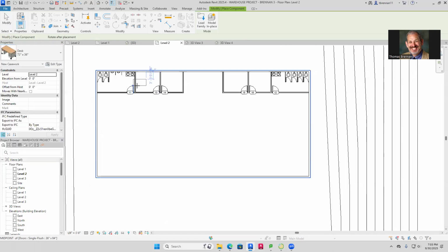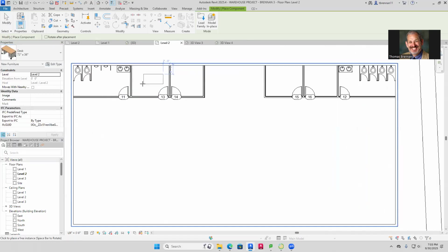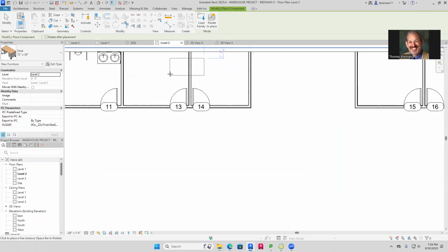Do you want us to stagger doors? You can put them in anywhere you want. Why does it say 1 hour next to the door? That's a great question. If it says 1 hour, that's a fire rating. Every time you're doing any kind of commercial building, and probably residential too now, the doors are rated for how long they can withstand a fire.